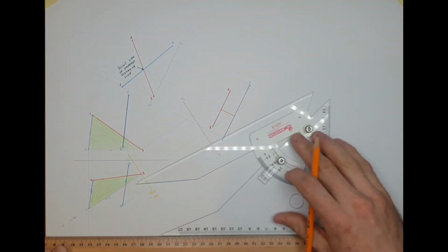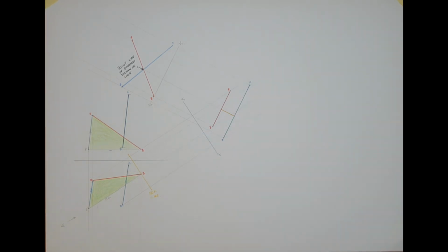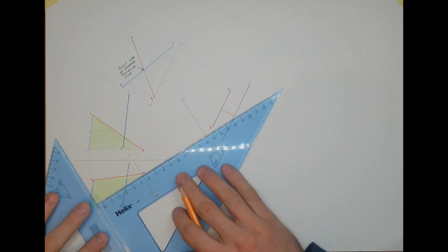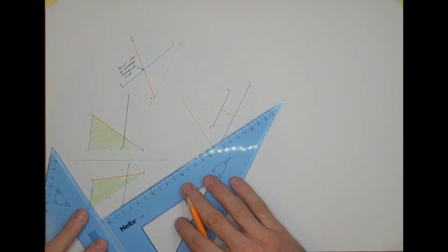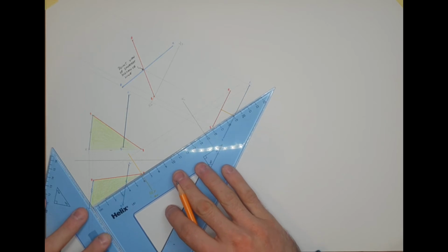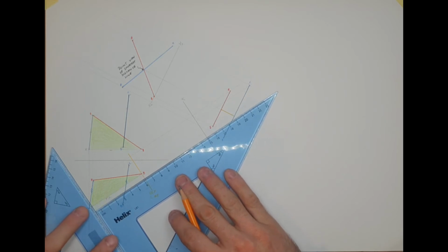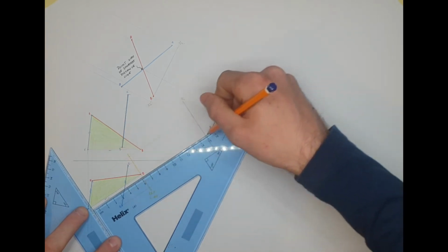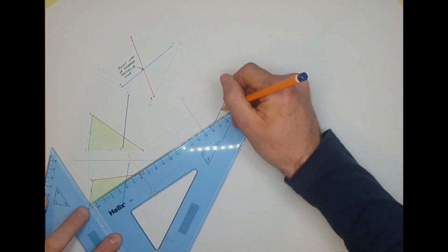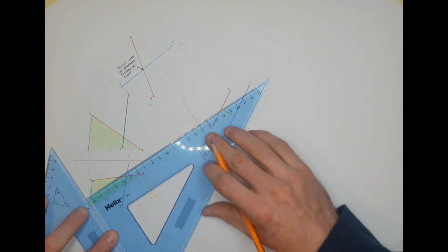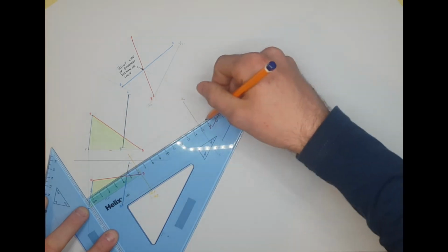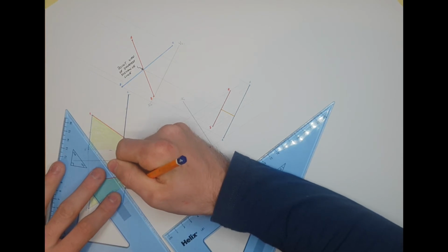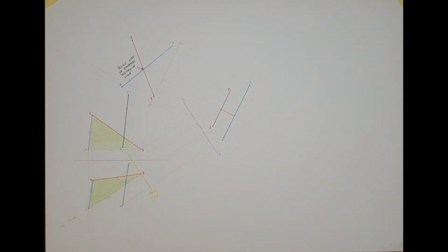I'm going to take it down to plan now. I'm not going to change my adjustable set square for that. I'll use sliding set squares, so parallel to my projections again, and just be very careful in your setup for this. The yellow line starts on the blue right there and goes up to the red right here. And get this one right, make sure it's accurate. So it goes from the red down to the blue. That is the shortest distance between those 2 lines.